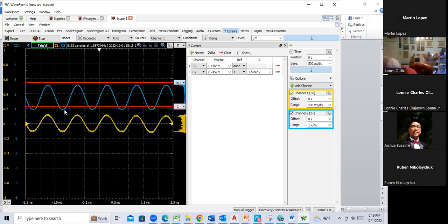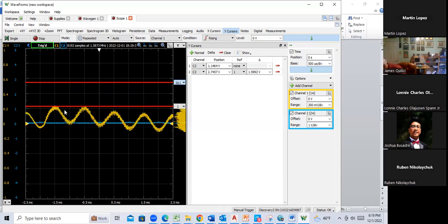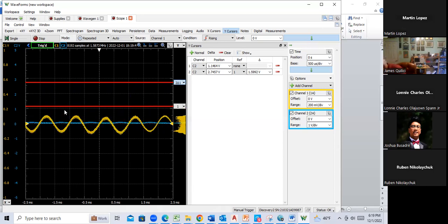Yeah, I'm going to put 2K back in there. And then I think I'm just going to reduce my emitter resistor again and see if I can get a little more gain out of it. My gain was 10, and so it's got a spec of plus or minus 10 on it too. So I want to get at least 9.